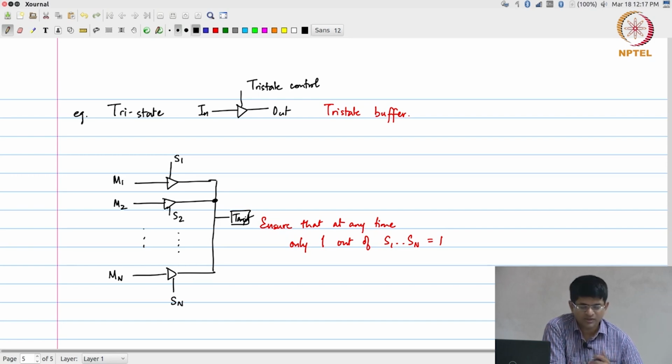Okay. So, in other words, both of these multiplexers as well as tri-state logic are two different ways by which I can implement a shared wire. Okay, that is all. At this point it is just a shared wire. It means that two of them are able to use the same wire in order to communicate with a third party. Okay, or n of them are able to communicate with the target, not between each other. Okay, but the moment I can do sharing of this sort, it should be possible to do it the other way as well. Okay.